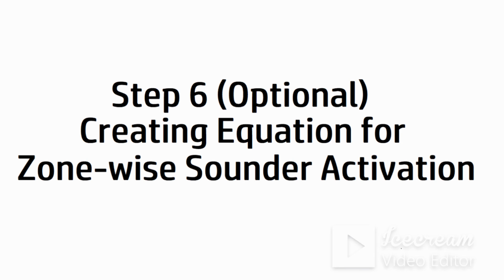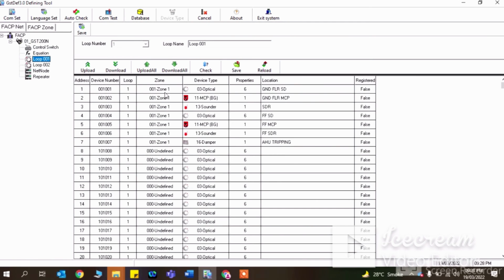My second scenario will be like this: in one loop itself, I may have multiple floors. For example, ground floor and first floor, two different floors. On the ground floor I have 3 devices, so I assigned a zone, and on the first floor I have 3 devices. My condition is, when the ground floor activates, only the ground floor sounder should activate. When a first floor detector detects, my first floor sounder should activate. That is my second scenario, or people may ask such scenarios.